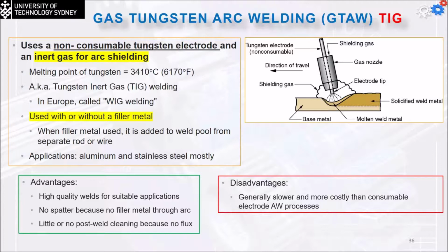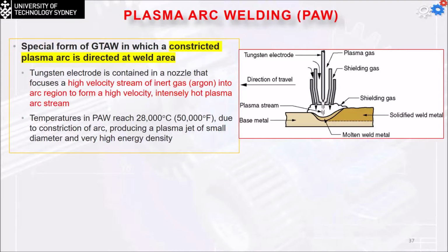We talked about plasma in advanced manufacturing technologies. Now, the plasma, once again, is a gas that is going to be energized and heated by using the tungsten electrode. So this is the plasma gas, and we have the shielding gas. We have the primary and the secondary gases. This one is going to make the shielding to prevent oxidation, and this one is going to accelerate the air and make the plasma arc.